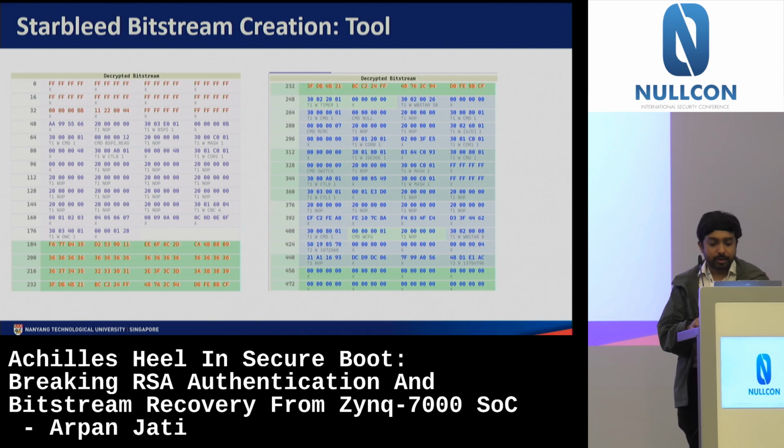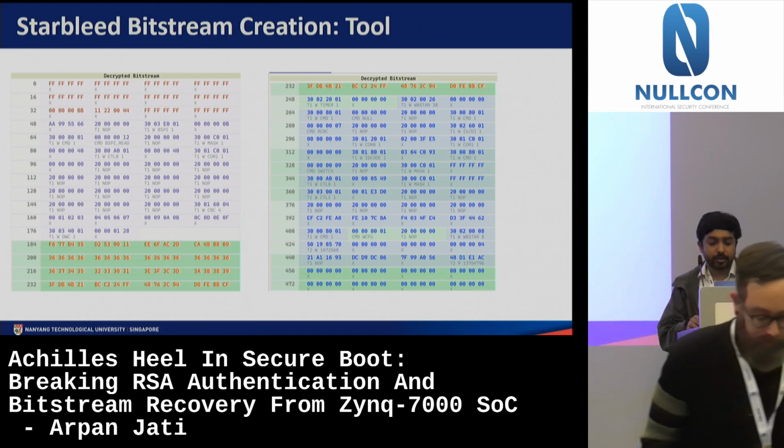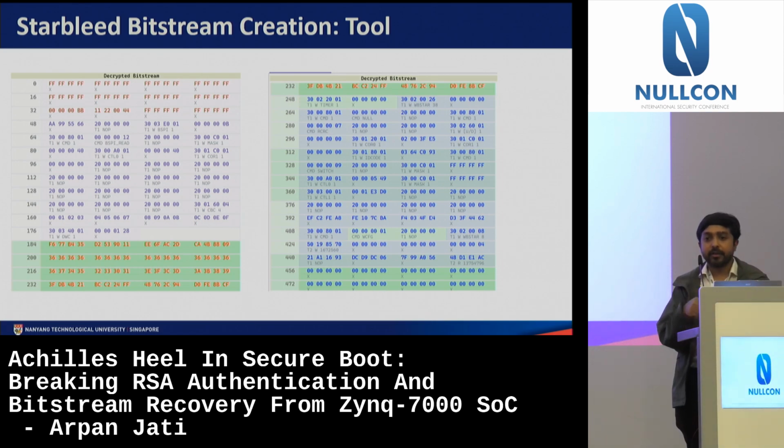And the important part is that you can see this in this command, the last line. The last line is like 48D1E1AC. This value will actually be found in the WBSTAR register when you read over JTAG. And now if this line is changed, like line 440, if the whole line 440 is changed by an unknown item, that will be decrypted and made available in the WBSTAR.